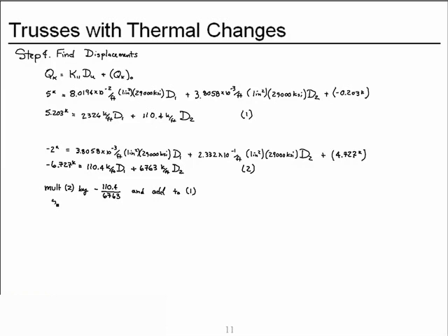So if I take equation 1, add to it this term times the left-hand side from equation 2, this quantity times this quantity, the minus signs cancel, and I add a 0.110 kips equals, and I have that term, 2326 kips per foot d1, and this term times this ratio means that I will subtract a 1.8 kips per foot times d1.